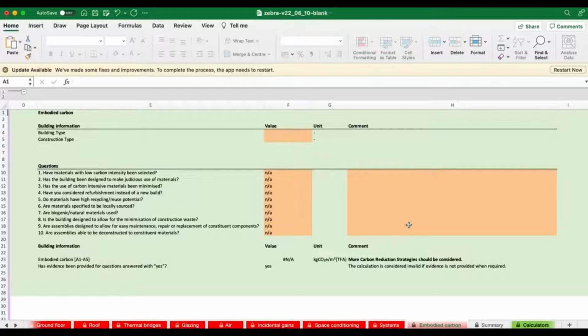And the kind of information that will require is the mass of concrete, the mass of steel, the amount of glass. Any details you can find about clip-on facades, units, carpets, etc. And you can just go into other people's software and work out the embodied energy of your building and copy it over here at complexity level 3.